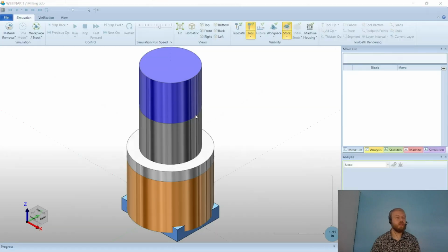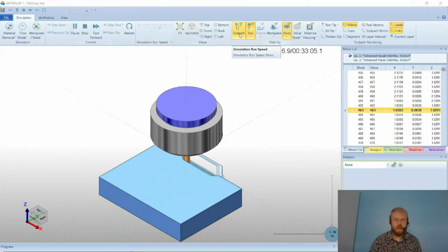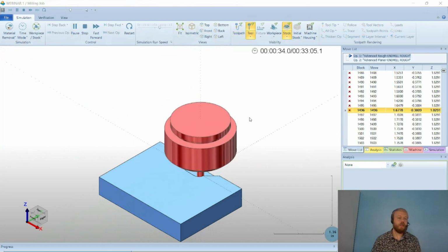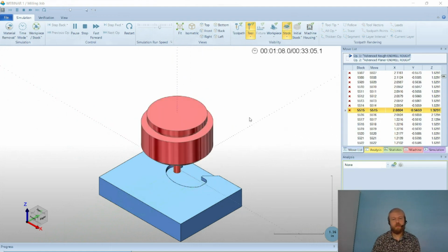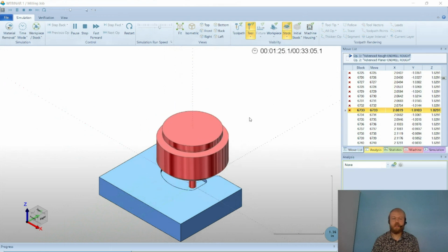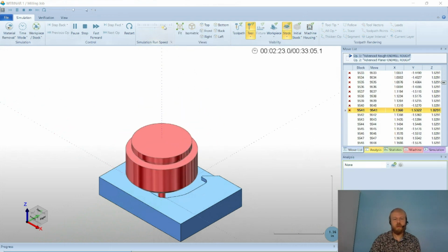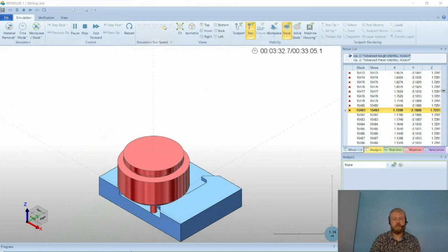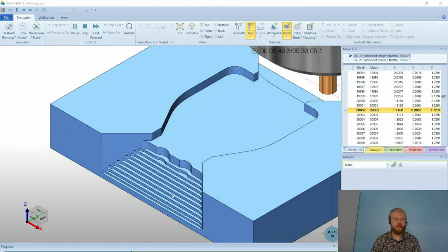And then we have gone through the Mill 3-Axis Pro with our advanced rough here, and a 3-Axis Pro toolpath for a finish with our advanced planar. Now the advanced planar in 3-Axis Pro isn't going to be the most efficient here for those tapered walls. We'll get into the 3-axis premium to see how to clean up these tapered walls a little bit better here.